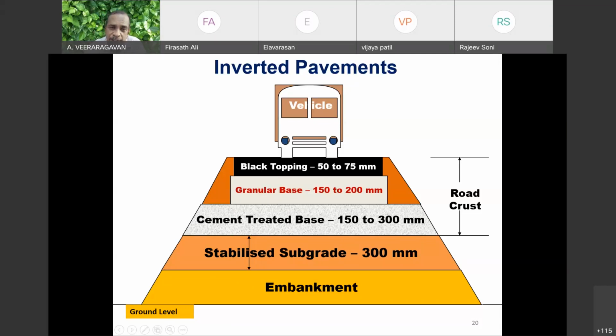So another solution is to improve the subgrade and provide an improved subbase, base course or subbase. That is the second solution which I am bringing in. So we talk about sustainability. We should learn how to bring in sustainability by reducing the virgin aggregate consumption and reducing the maintenance requirement, in terms of material and in terms of cost. Both are possible by stabilizing the subgrade or by stabilizing the base or the subbase courses.